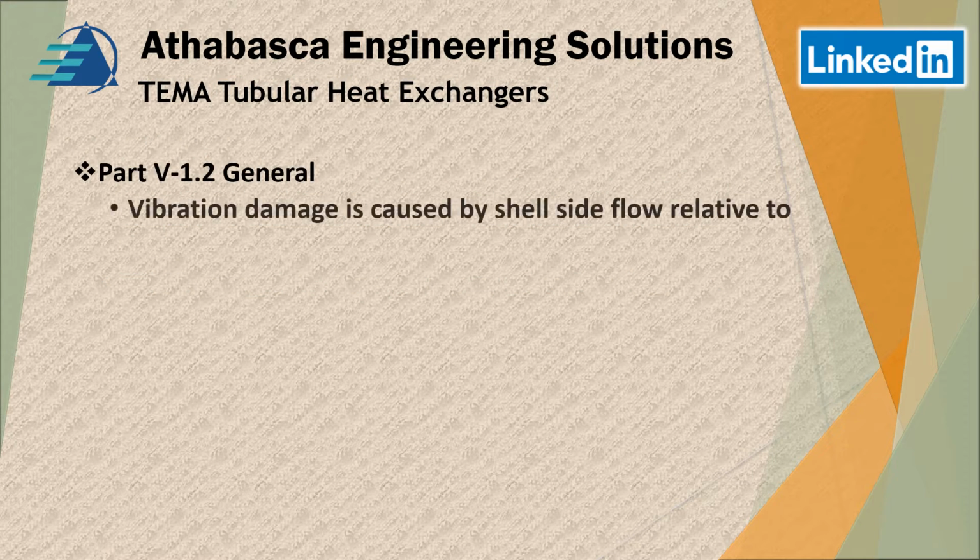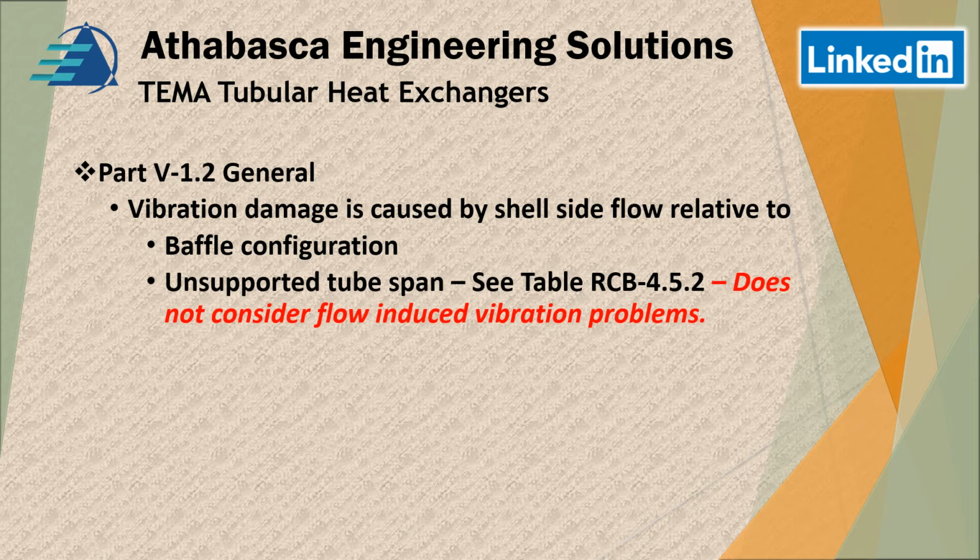In general, they say vibration damage is caused by shell side flow relative to the baffle configuration and unsupported tube span. And if you refer to table RCB 4.52, there's some design information. There's a caveat here: it says it does not consider flow-induced vibration problems.